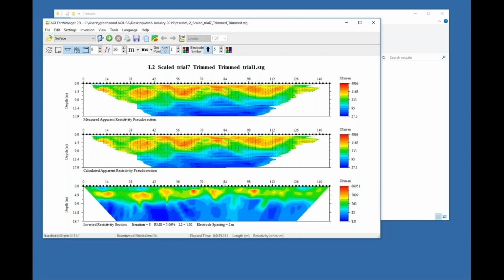If there's a particular area in a large domain like this that's hundreds of meters long and 20 meters deep, if there's a particular target in here that you're concerned with, the best way to look at it is to take a subdomain and solve a new model, because this entire model space has to fit the smoothest solution to this forward. This difference here is our RMS. So it has to search this entire model space. So you'll end up with a larger domain, a smoother solution, than a smaller domain for the same target if it's a small cohesive target like this.